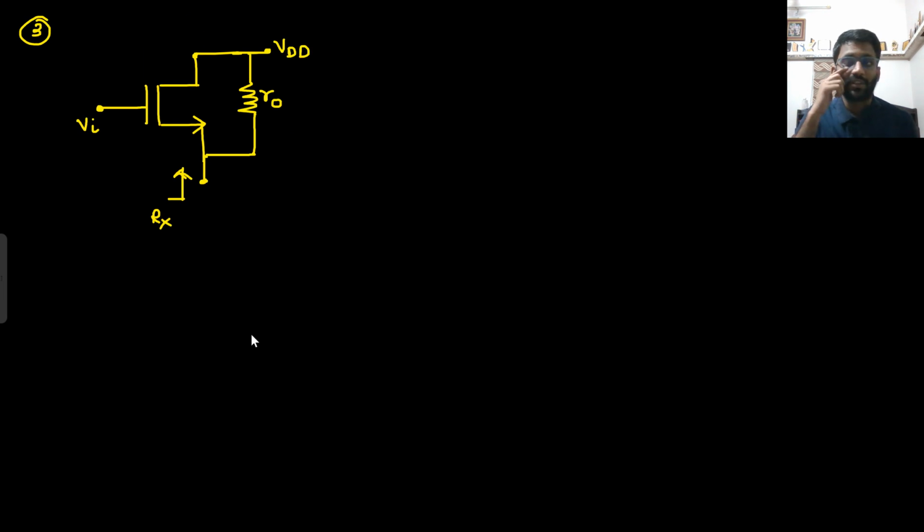Let's come to this question now. Now these kinds of questions are considered to be tough as per the GATE aspirant. They think, okay, what kind of amplifier is it? Do I remember the expression? Nothing, no need to remember anything. We know the simple concept. What are we asked to find? We are asked to find the resistance from here. What we will do? Short circuit the independent sources. Vin is the independent source. I will short circuit it.